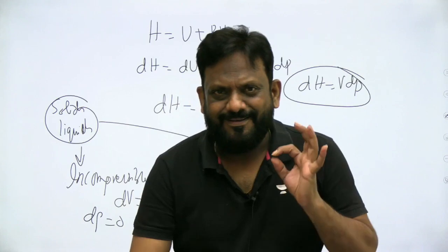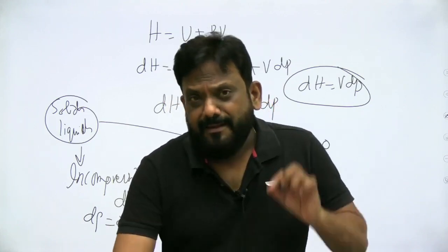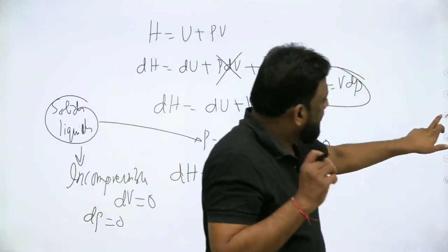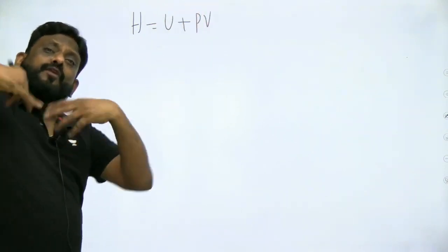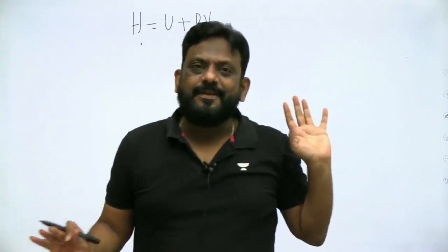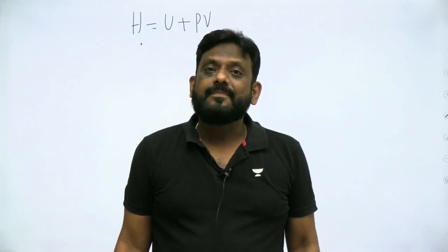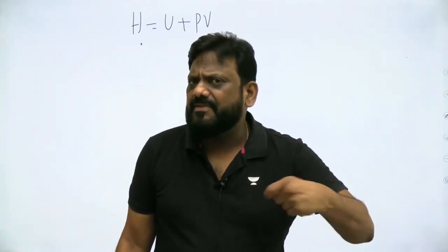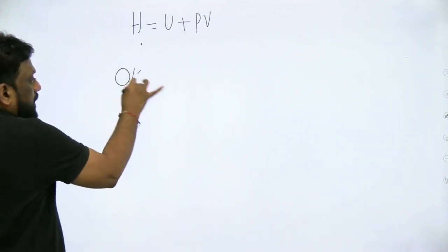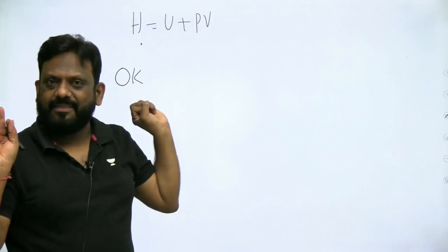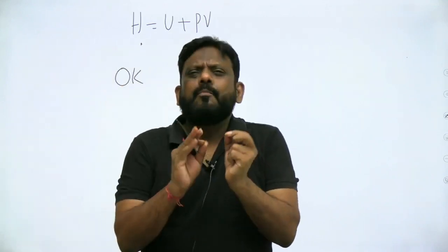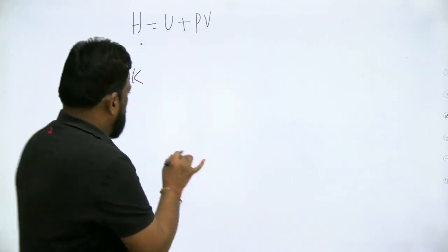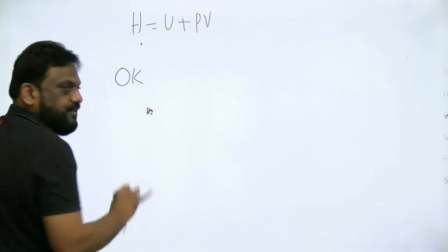So to sum up, what is physically enthalpy? It is U plus PV. And the last beauty: one student again asked me a question, sir, you wrote enthalpy directly as U plus PV. We can visualize U, but how suddenly did PV come to your mind? The explanation can be given something like this. At absolute zero, the question is how this PV came into the picture. At 0 Kelvin, there is no molecular activity, and the volume will shrink to almost zero. I'm not saying zero, almost.